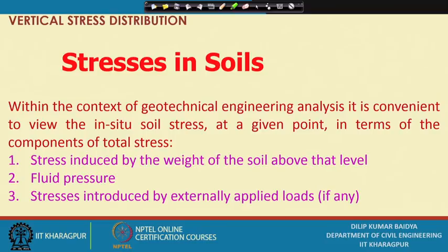That means, soil may be considered at a depth of 5 meter, but above the 5 meter, the entire depth of soil has weight, and because of that weight at 5 meter depth, there will be some stress. So, that is one, that is because of the self weight of the soil.